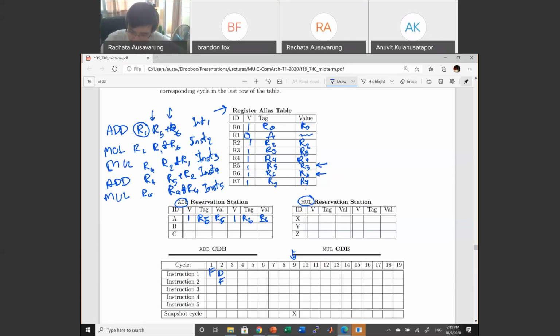Instruction 1 is going to be the first cycle of execute. Instruction 2 is decode. Instruction 3 is being fetched. Right? When you decode instruction 2, what do you have to do? You go and look at instruction 2, which is a multiply, right? So you go here, station for the multiply, because we said that everything is done during the decode stage.